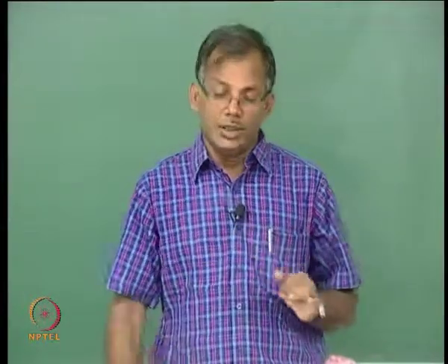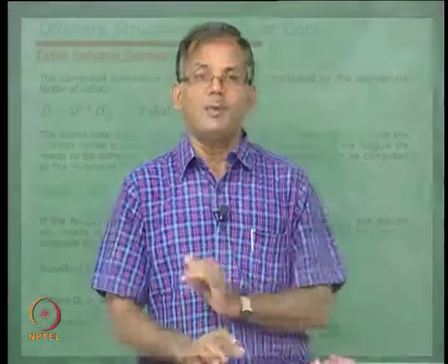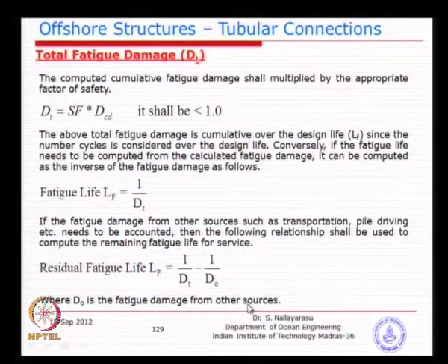It does not only apply to transportation, which I have mentioned here, but to any other sources. If you have already got some fatigue damage due to other sources of loading, then you just deduct it from the fatigue life at the final service condition. Many times we are required to do this.